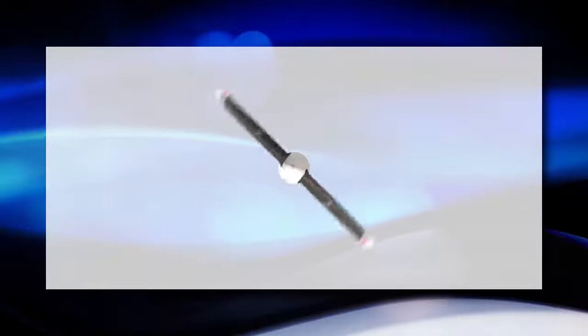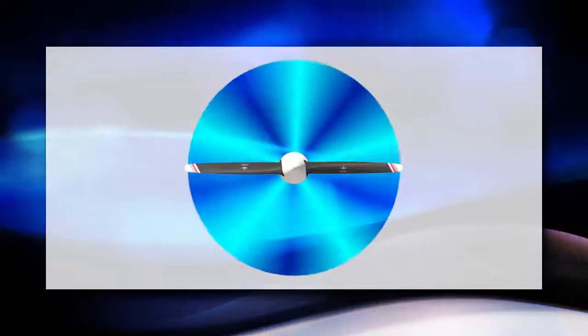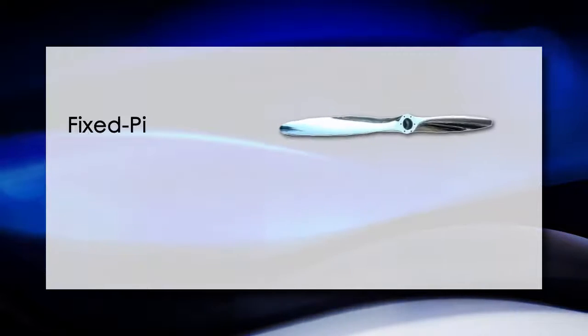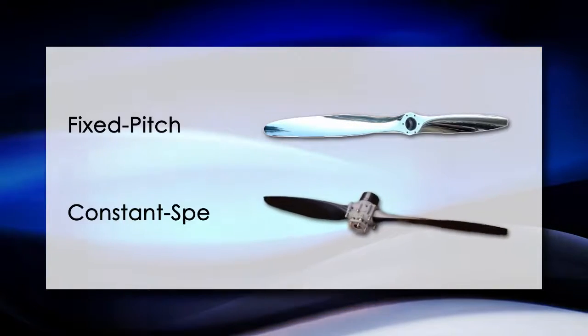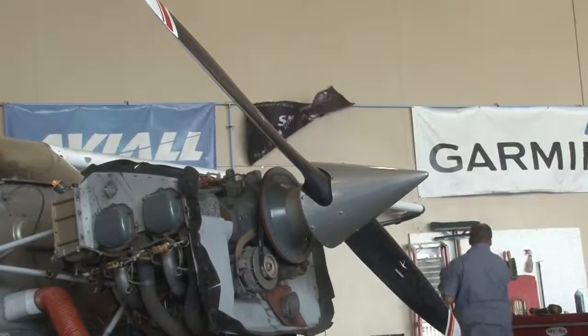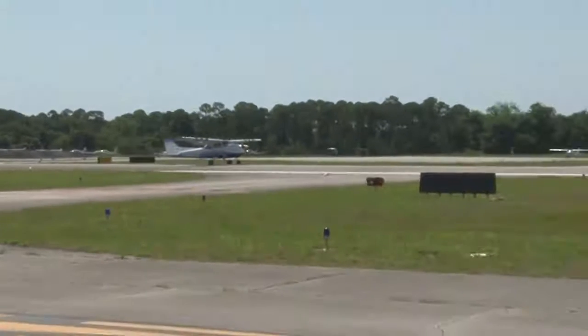Since the propeller rotates around its hub or center, the further the propeller extends out of that hub, the faster it spins. To create equal force throughout, manufacturers twist the blade. There are two major types of propellers: fixed-pitch propellers and constant-speed propellers. The Cessna 172 is equipped with a fixed-pitch propeller. This means that the pilot cannot manipulate the propeller blade.